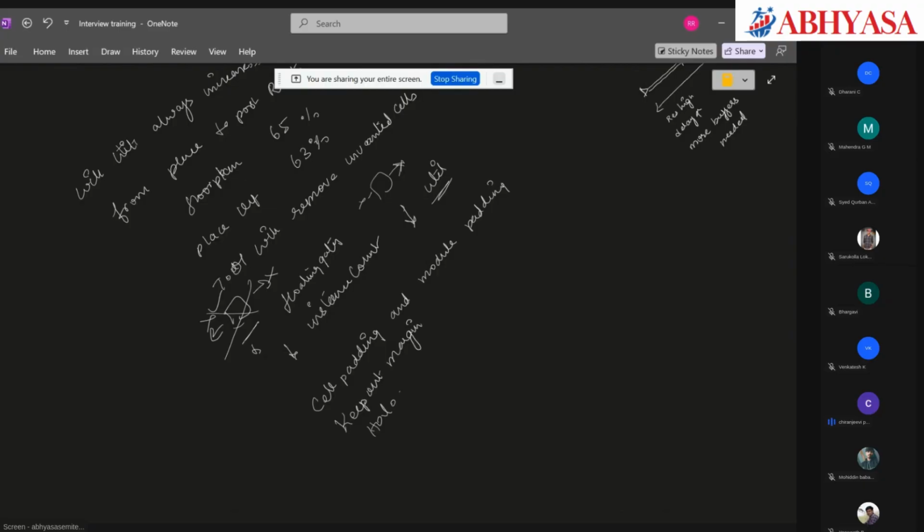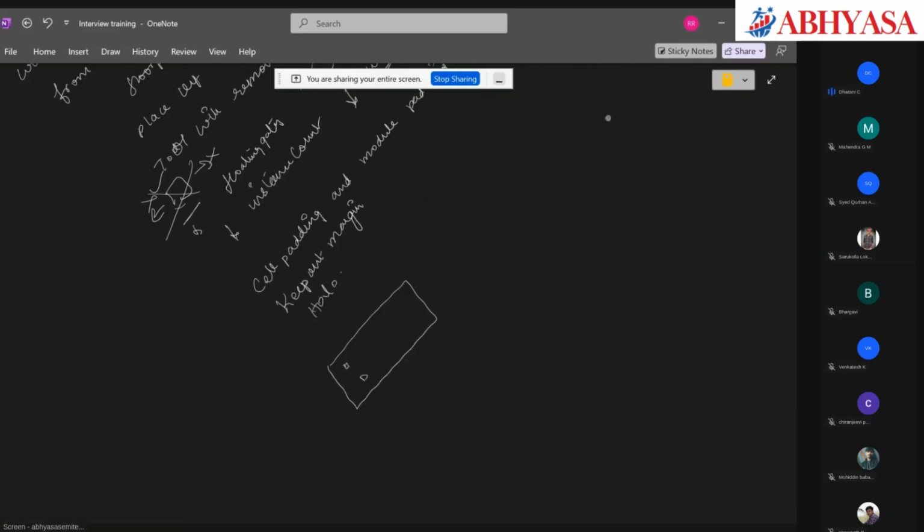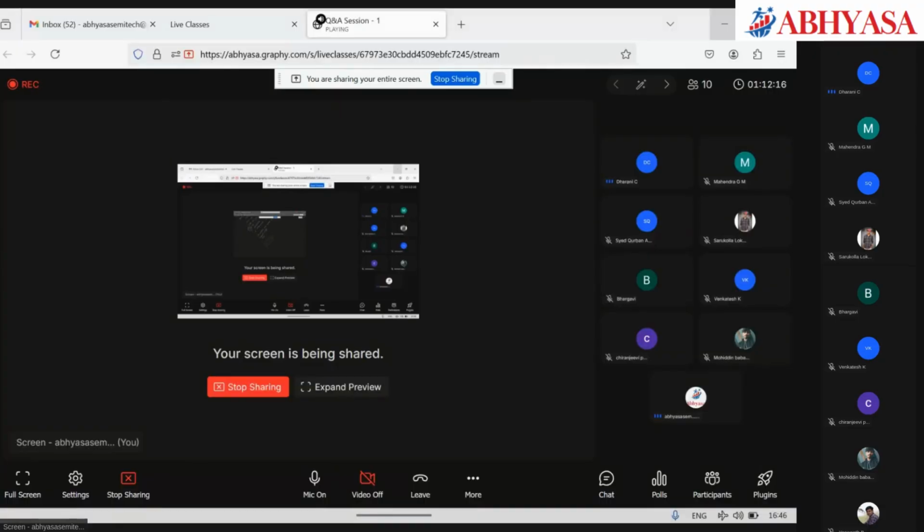Why do we define some boundary to the standard cells or macros, sir? So boundary will already exist, I guess, for standard cells and macros. When there are high pin density cells, we use keep out margin around a cell. For what reason? To overcome that congestion problem.